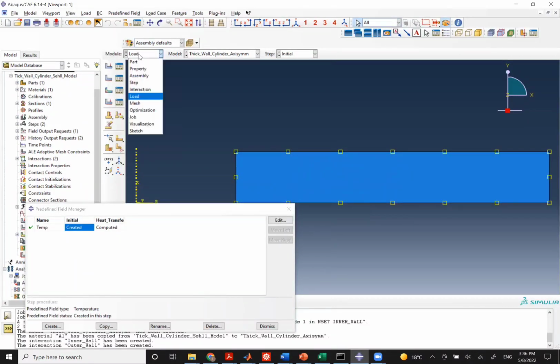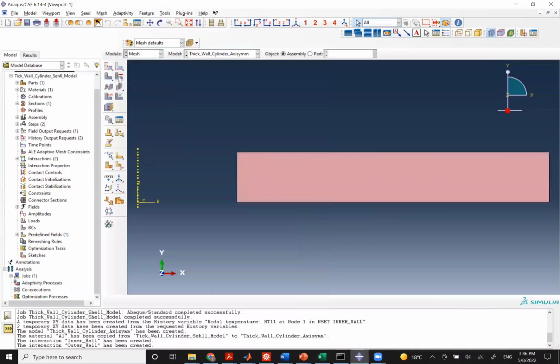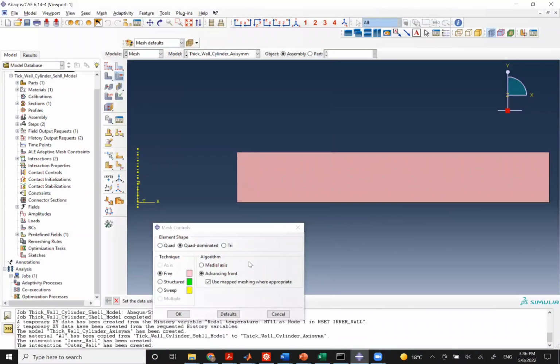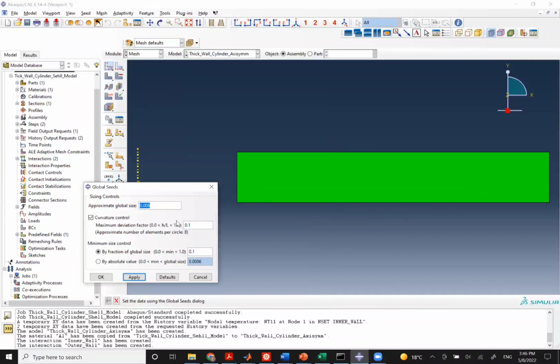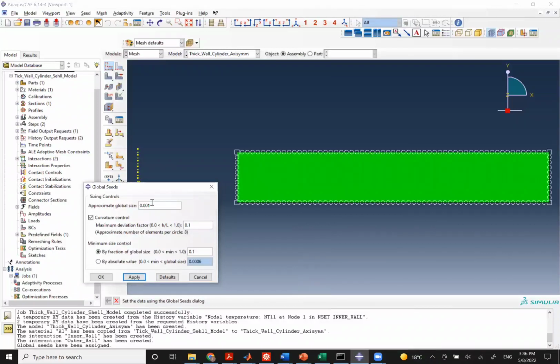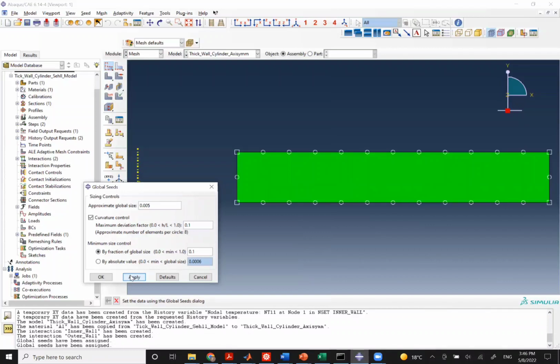All right, and let's go to mesh. And I believe we can have a structured mesh right away now. Quadrilateral, structured, nice. And let's have an element size of 1 millimeter. So previously we had 5 millimeter. Let's have 5 millimeter. Well, that's coarse, because now we're having quite different dimensions on that one, that circle. So let's have one.